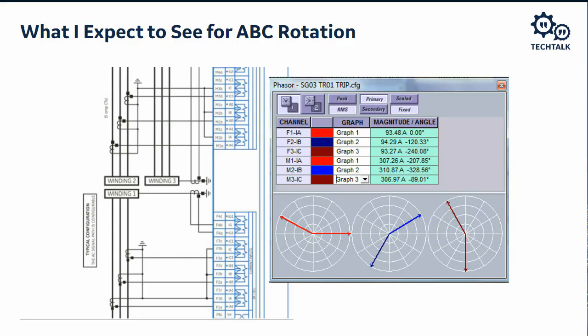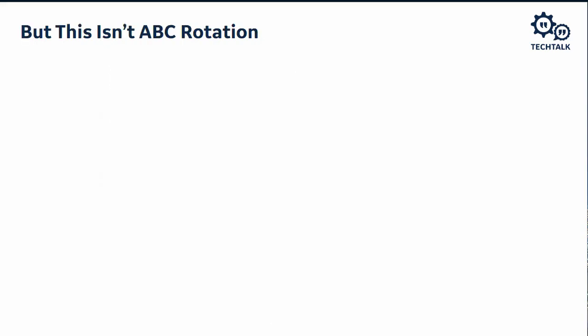because if we look at the left, the way that we wire the CTs is we're wiring polarity to the side of the CT that is away from the protective equipment, which is typically marked as polarity on the CT. And since we're doing that, the current is flowing into polarity on one side of the transformer, and flowing out of polarity on the other side of the relay inputs. So we expect to see that 180 degree phase shift. Instead of being at minus 30, we expect it to be at minus 210, which is what we're seeing in this screen. Now, what we were seeing on the previous slide, though, was that we weren't sitting at minus 210, we were sitting at minus 150.